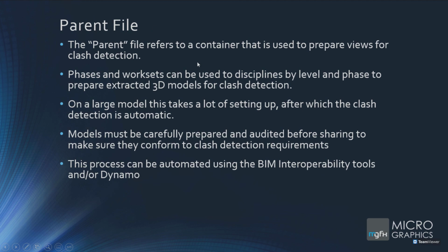The parent file refers to a container that is used to prepare views for clash detection. We've just seen that, because we can manipulate the worksets within the files and isolate elements with which we want to clash detect. Phases and worksets can be used to organize disciplines by level and phase to prepare extracted 3D models for clash detection. That's what we've done.